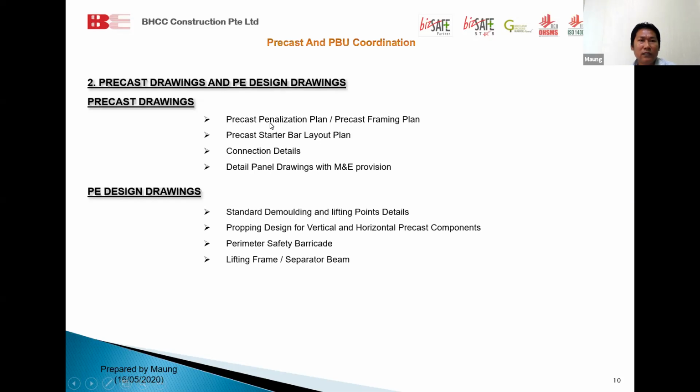For the HTV project, you need to submit only two drawings, the framing plan and the connection detail panel drawing, because the HTV consultant and HTV already have their standard connection and bar. So we need to submit our precast framing plan and the detailed drawing only.